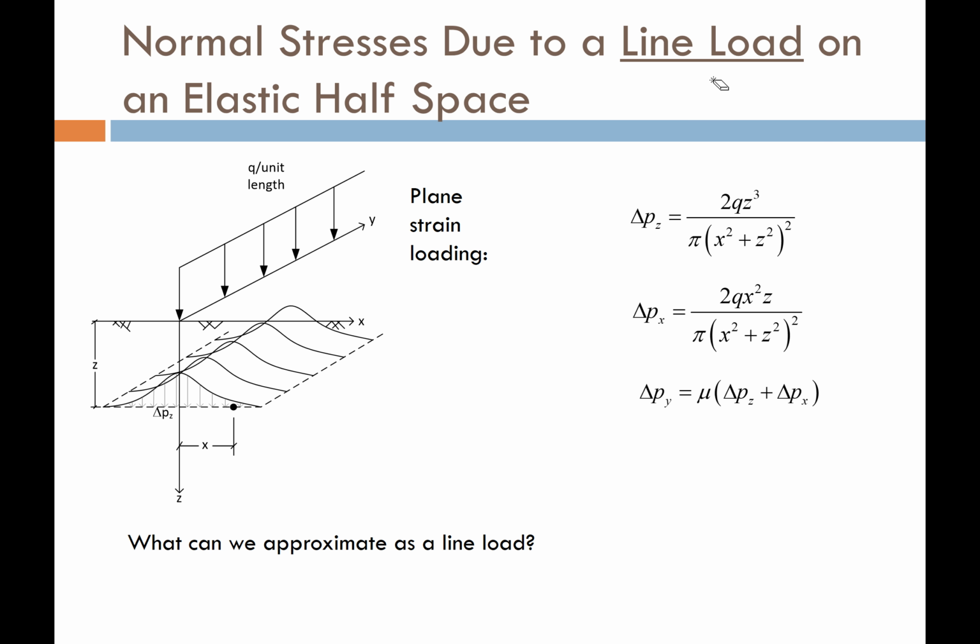So when we do that solution, what we're doing is we're just saying the line stretches out infinitely in one particular direction. In this case, it's in the y direction. And you can see that the load just follows along that line. And what that's going to do is produce a series of stresses that are going to peak right beneath the center of that line in the y direction. And as you move away from the y, it's going to produce smaller and smaller stresses, as you can see on this stress distribution down here.